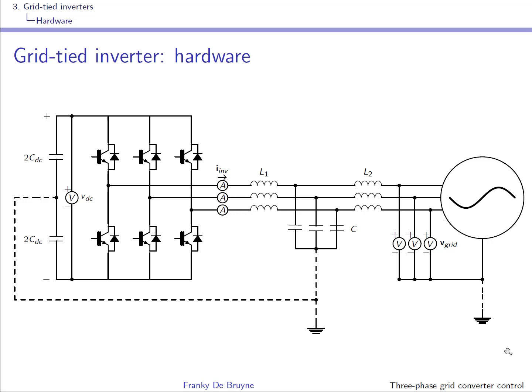Well, we've seen in the course of state space control that if you would like to model an LCL filter, you need actually to put in your state vector three things. Well, the current through L1, in this case we'll call it I inverter.